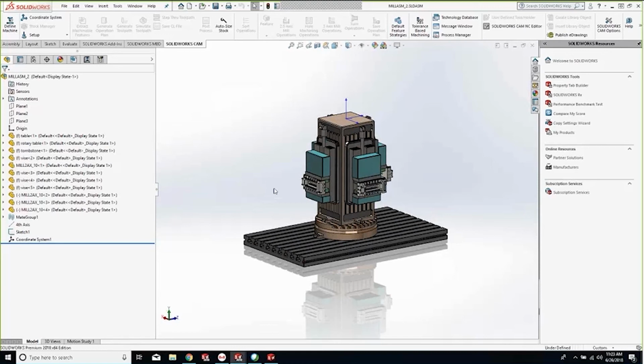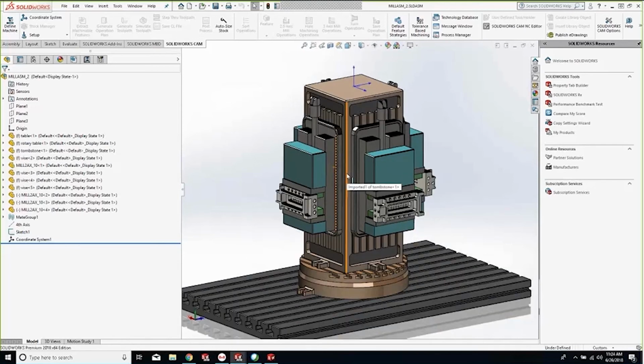It also gives you the ability to work with Solidworks Cam configurations, as well as high-speed machining volume mill, so for 2.5 axis. But one of the major benefits that I see with the Solidworks Cam Pro module is the ability, working within an assembly, to have multiple bodies. What you can see here on my screen, I have a tombstone, I have multiple Kurt vices, I have the table identified, and then I also have my parts, my work pieces that are going to be cut.